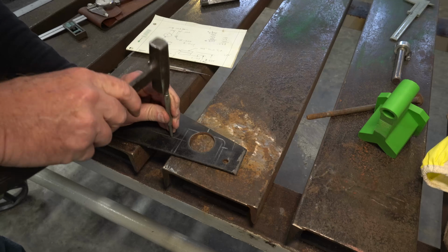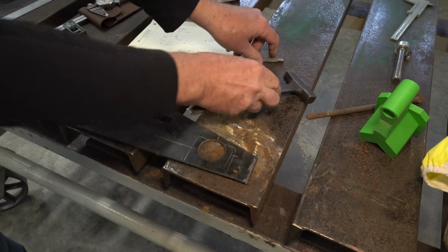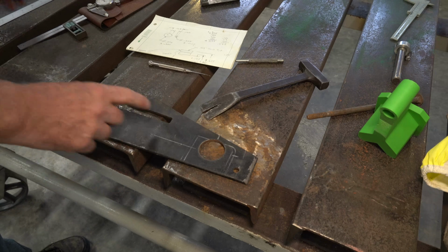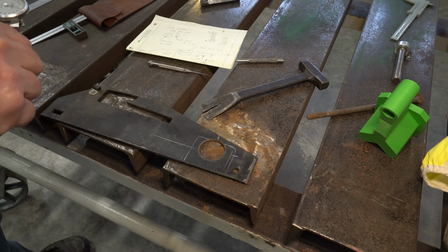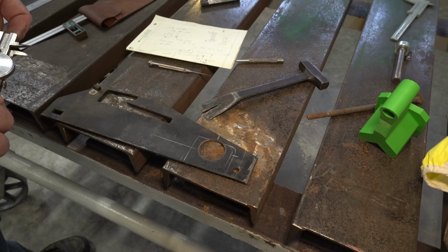And from there we'll see where it is. Now from here we're going to come over. This will be the hole for the pin. We need to come 0.668 inches. So I'm just going to use the pair of calipers and set them on 0.668.